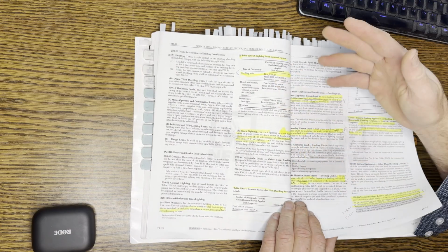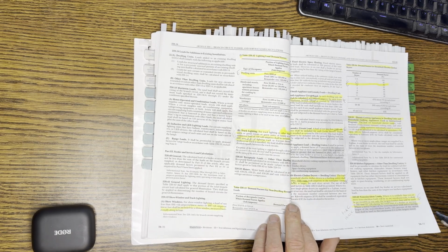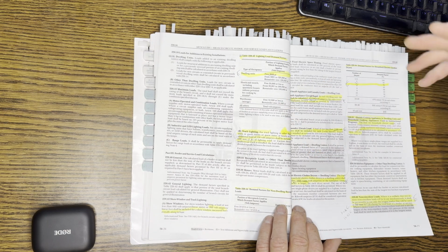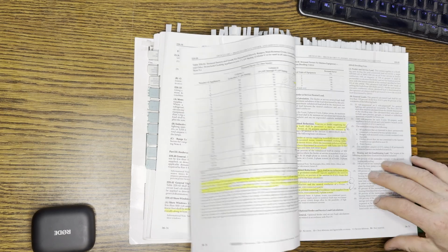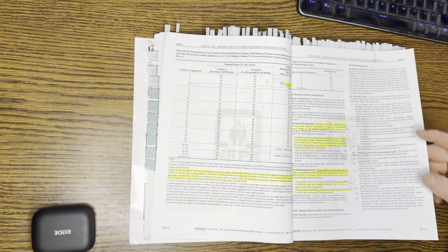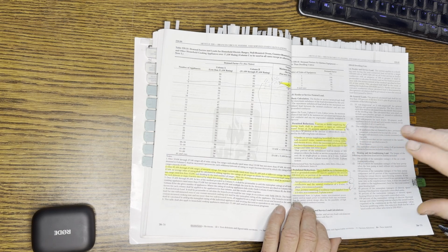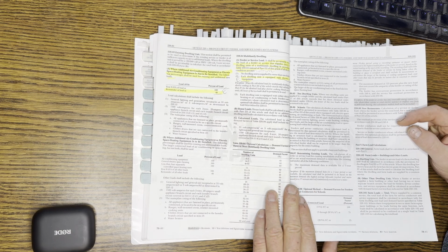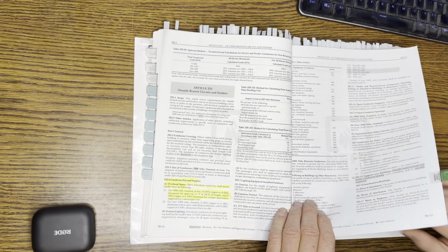So, lighting load calculations, some of this stuff. Within the online test, I do have some calculations you're going to do, like lighting load calculations and stuff like that. But just basically go through, know where this is: demand factors. These help you derate your loads. Know the rule for dividing your voltage by square root of 3 for 3-phase. It's not going to be in here, but look that up. Know how that works. That's a question you're going to be asked on. I may not have that represented, but know some basics about that.